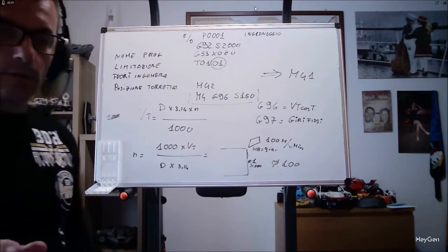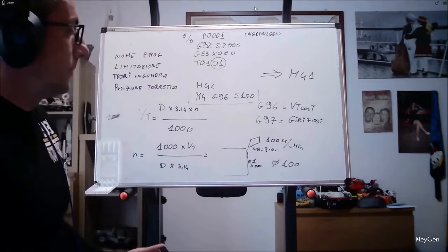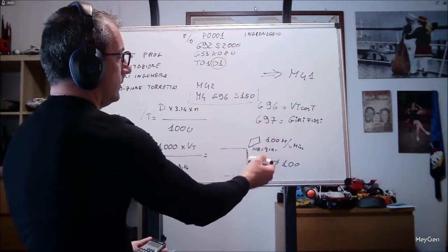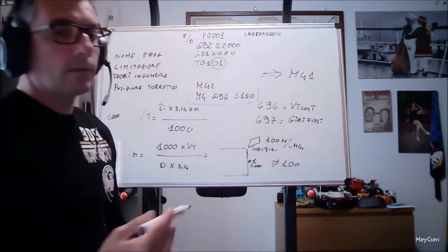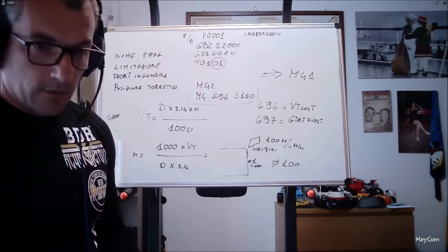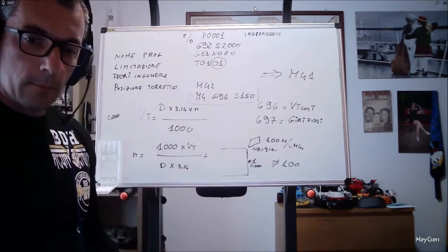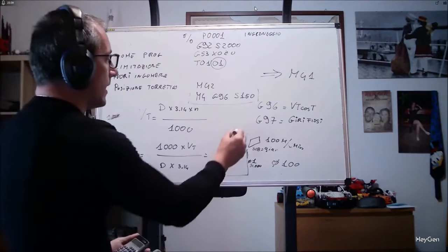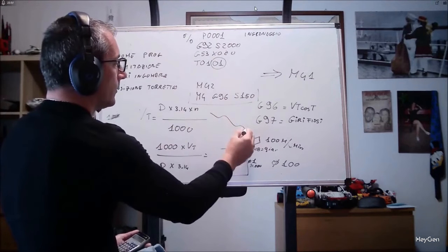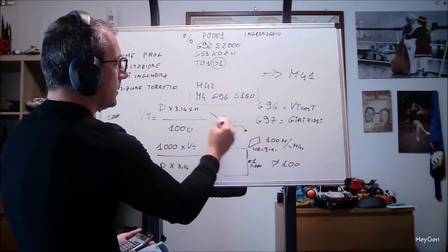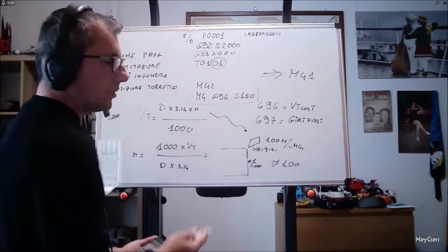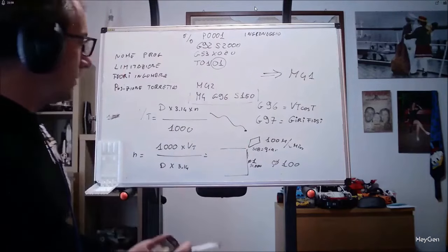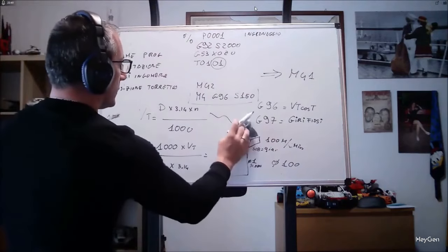If you are already working and are in the workshop, just perform a facing operation to physically feel the machine accelerating as it works towards the center. So even when we create a profile, if we start here at 1000 revolutions, we will be, one minute faster, at 500, 600, 700 RPM, like this.